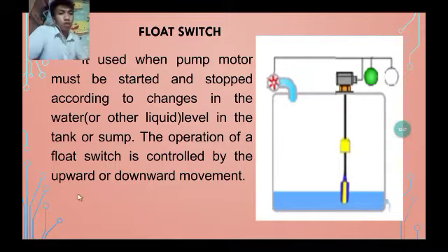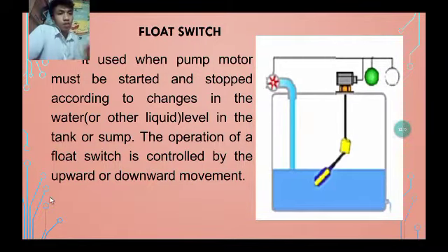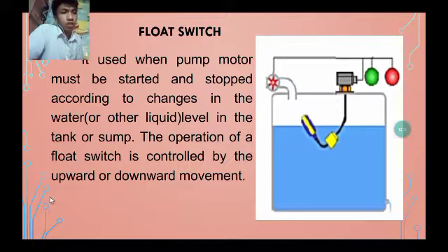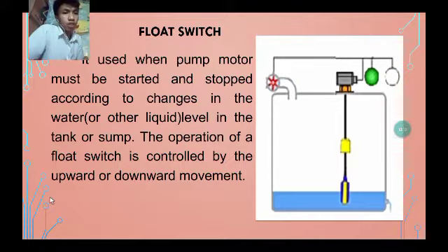Next, float switch. It is used when the pump motor must be started and stopped according to change in the water level in the tank or sump. The operation of a float switch is controlled by the upward or downward movement.